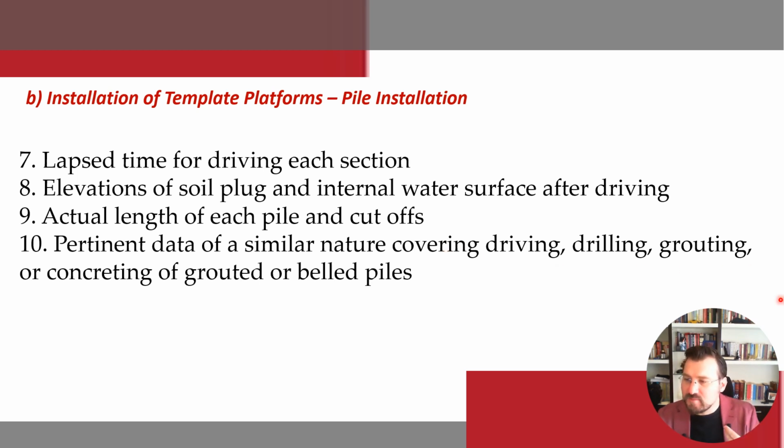So after some time, when the cement is fully filled in the annular space I'm talking about, the cement starts coming out. So the samples of the cement slurry going in and coming out of each leg and sleeves are taken and the cubes are made out of them by placing in wooden frames, which are later sent to hardness tests to get an idea of cementation in annular space. So divers survey the cementation of sleeves, right?